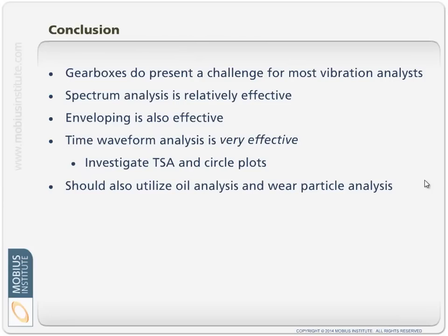Anyway, this has been a very long presentation. I hope you've hung in there with me. I normally try to keep them a bit shorter. This is a big topic, so I hope you found it useful. A few quick factors. You do have to think about gearboxes very carefully to make sure that where you place your sensors, you're capturing the frequencies of interest, there's a good mechanical transmission path to that point, and that your measurements are being set up correctly.